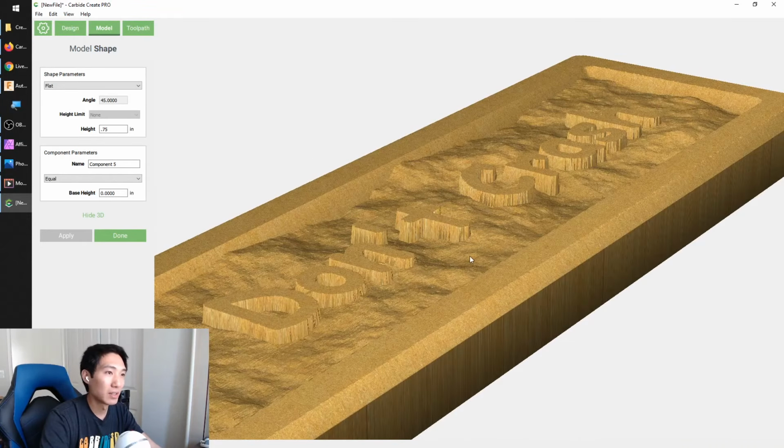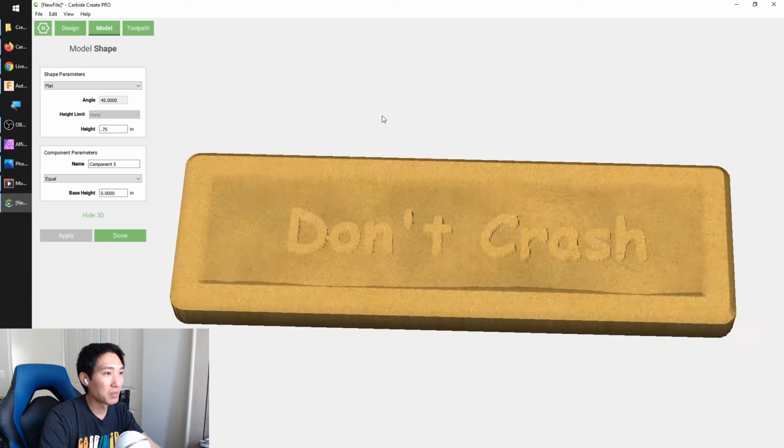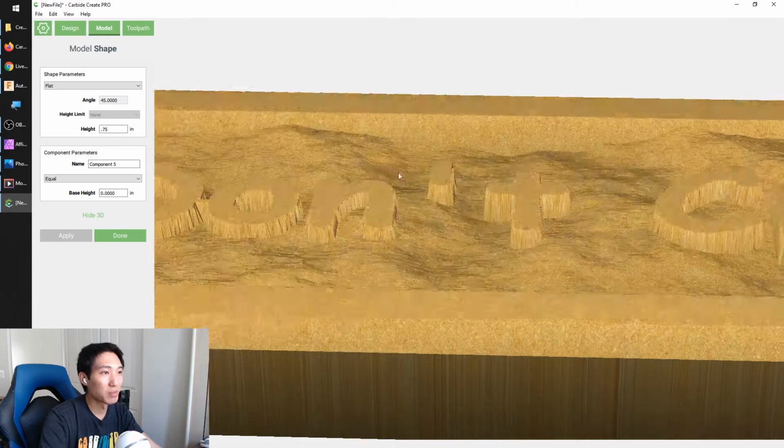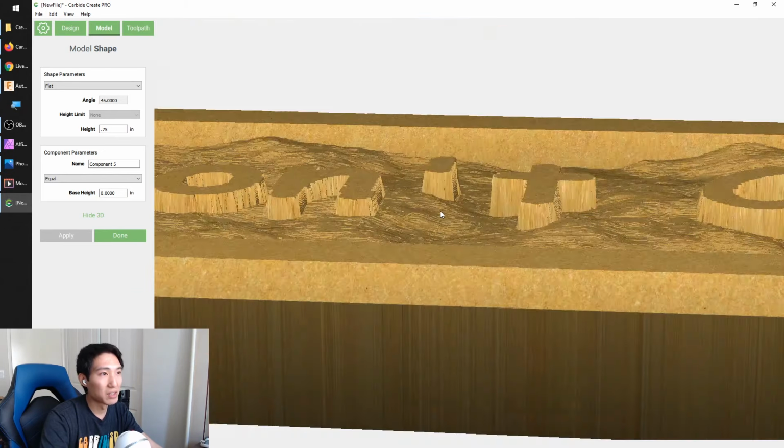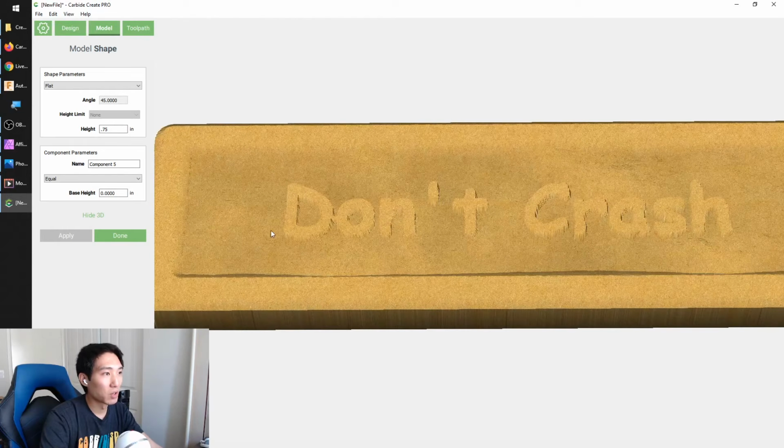And there's a lot you can do with it, especially with the textures, choosing how you apply it. If maybe you want to create a border around the text, because right now if you try and machine this, around these corners, if you use a ball end mill, there's going to be a little fillet around your text. So what you could do potentially is leave a little relief area outside the text that doesn't get textured. So just little things like that.